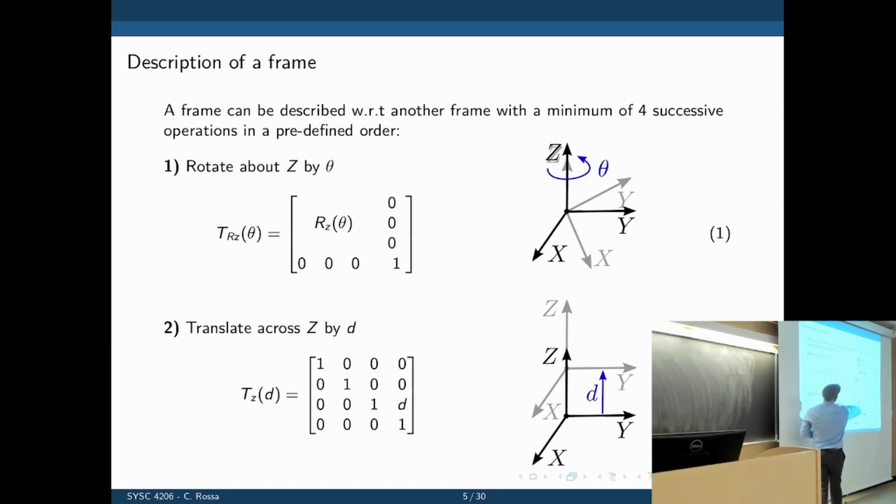This is basically saying that frame P is rotated about Z with respect to frame A by theta, and R is then the 3 by 3 rotation matrix that accomplishes that transformation. But we need the full description of those frames, so we also need to consider the translation. So that's the vector that goes in here. You just notice there, it's all zeros because the origins of those frames are coincident. So we have a vector of 0. So the displacement between them is 0.